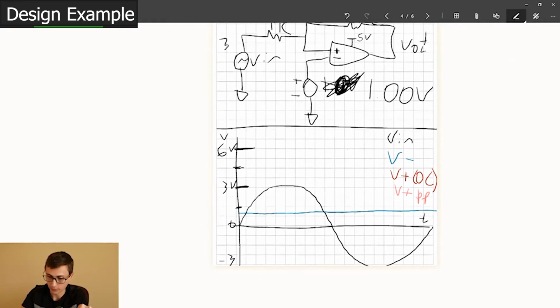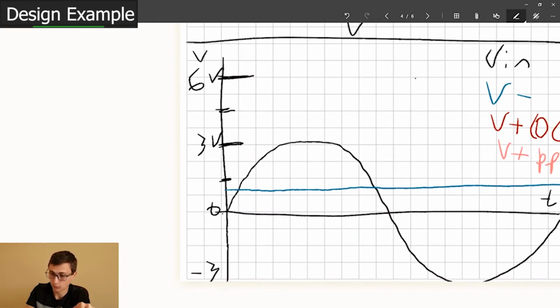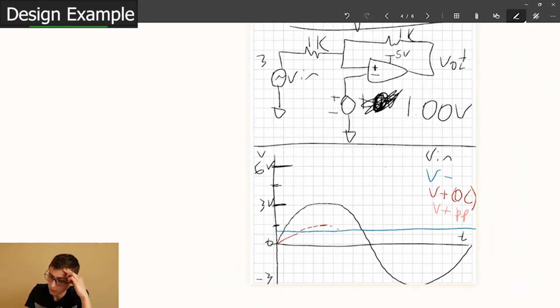For the open collector comparator, we're starting this off with clamp to ground. And what we're going to see for this waveform is that it goes up with what would be a peak voltage of 1.5 volts. I'm just going to dash that. And we're going to draw this solid up to there. Okay. But what do we see where I've dashed this? Once we hit that threshold, what's happening? Well, in that case,